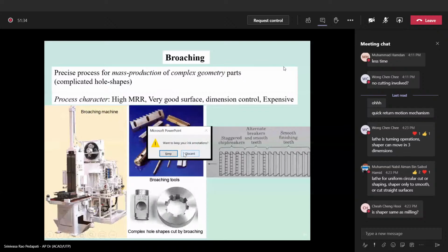Same purpose, so both of them have the same surface characteristics, metal removal rate, etc. But in the case of a planer, you can adopt multiple tools. You can also adopt multiple tool heads for cutting in the reverse stroke. That is the basic difference in terms of applications.